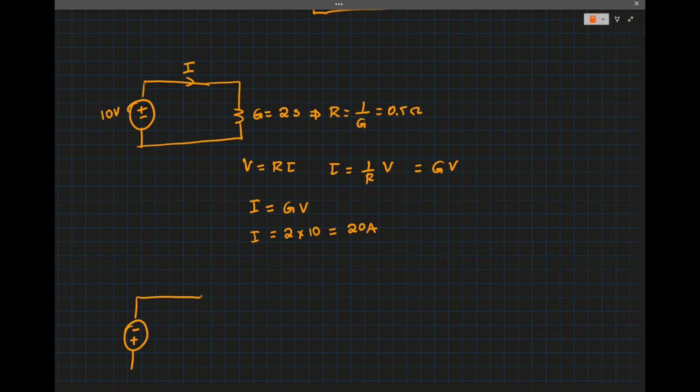Okay, and you have this resistor, and we label the current going that way, I. Which is an arbitrary direction that we give to the current, because in networks with many components, the direction of the current is not known until you calculate the value, and if it's negative, then the direction of the current will be the opposite.